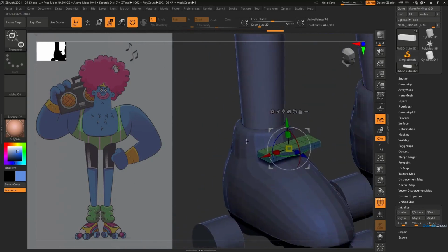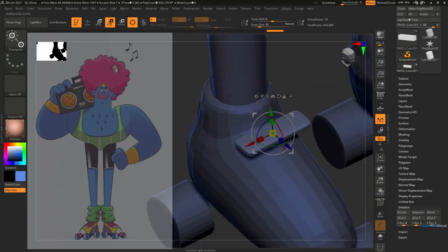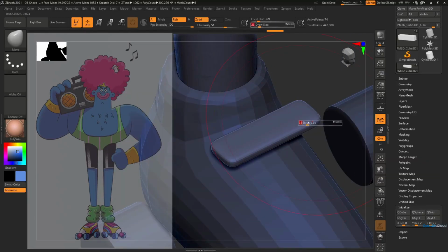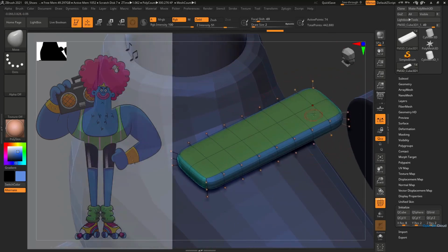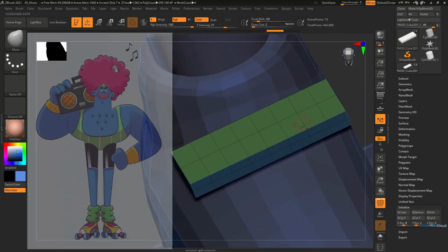Click on the D key and turn on Dynamic Smoothing. It's almost identical to Subdivision Surface in Cinema 4D. If you turn on the grid display, you'll see that the initial geometry isn't destroyed and you can adjust it. You can press Shift-D to turn off the dynamic smoothing.